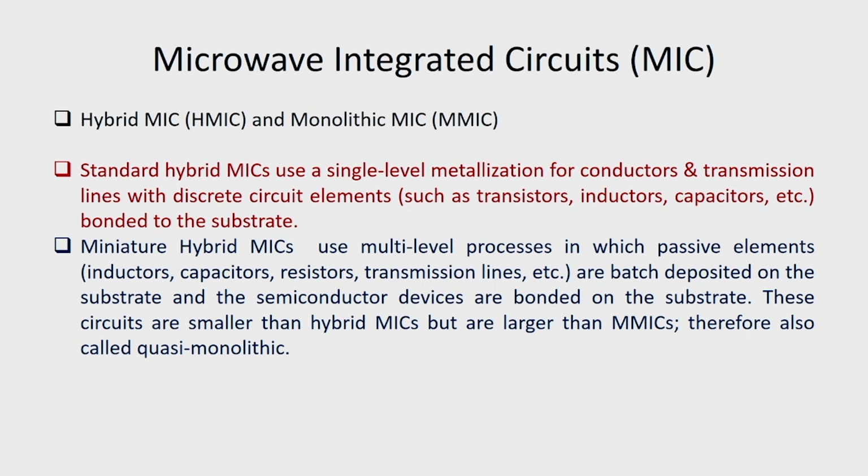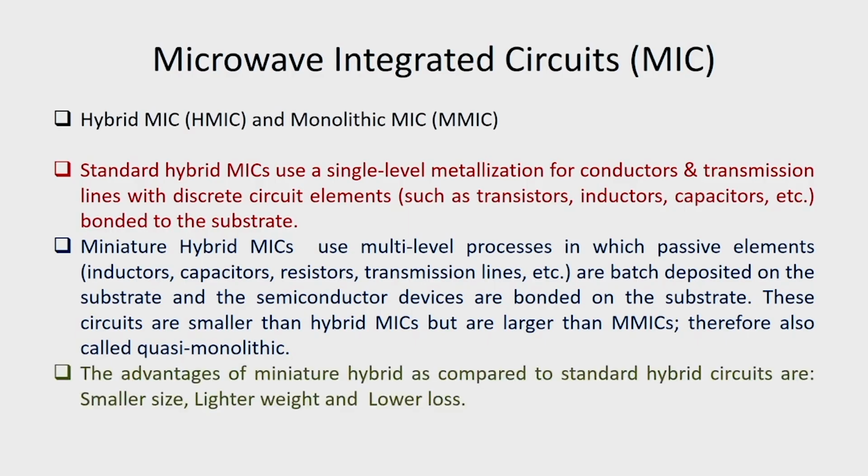These circuits are smaller than hybrid MICs, but are larger than MMICs. Therefore, they are also called quasi-monolithic. The advantages of miniature hybrid as compared to standard hybrid circuits are smaller size, lighter weight and lower loss.